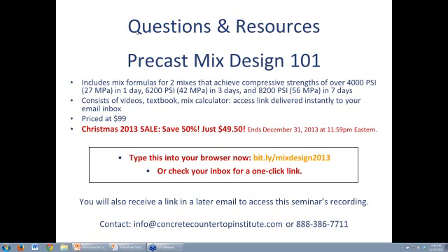Do you recommend a power blanket as a heat source for curing in a colder environment? Do they tend to heat slowly enough to encourage good curing? Power blankets are big, expensive electric blankets designed for outdoor concrete work in very cold temperatures. So yes, they are designed to heat slowly. Do I recommend them? I think they're a big waste of money. They're $700, hundreds of dollars a piece. I think it's kind of silly to spend that kind of money. Some people think it's important. I've never ever had to do that.